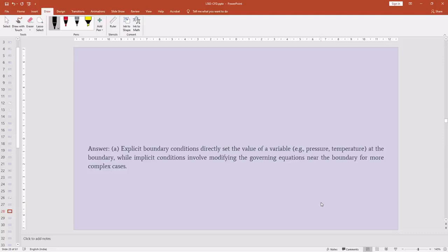That I actually need to check. It won't be very intense, because once you know the CFD methodology, we have a geometry, we discretize it, and we get algebraic equations that we have to solve. Solving these algebraic equations cannot be done manually. To reach a certain level of accuracy, we have to iterate n number of times.